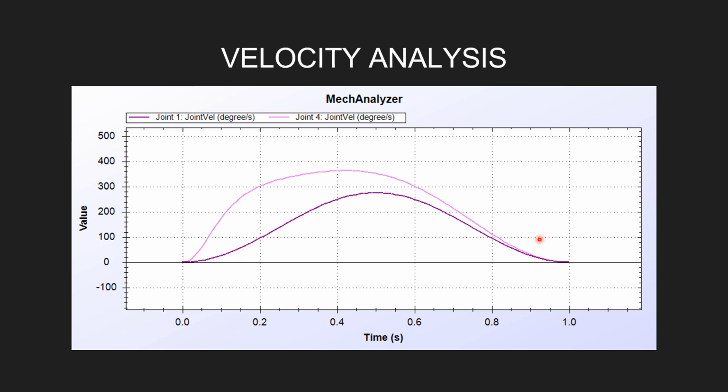And the last thing to note here is that our input and output velocity plot, if you can notice, is almost similar to the harmonic motion graph. This way, we can ensure that there is no sudden spike in velocity, no sudden acceleration or deceleration in the door movement while it is closing or opening. This way, the door can be safe for people to use, as they can predict the door movement.